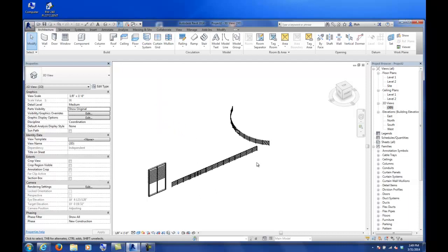The railing tool has some more advantages. Basically, the tool is a way to repeat a post every now and then, for some kind of pattern. But it then takes your rail system and makes it into a sweep. So your sweeps, as you know, can be a continuous element, so that it'll actually follow any kind of curve or anything that you happen to do with it. The other advantage of the railing is that the railing will follow stairs, and it's also going to follow ramps and any kind of inclined surfaces.